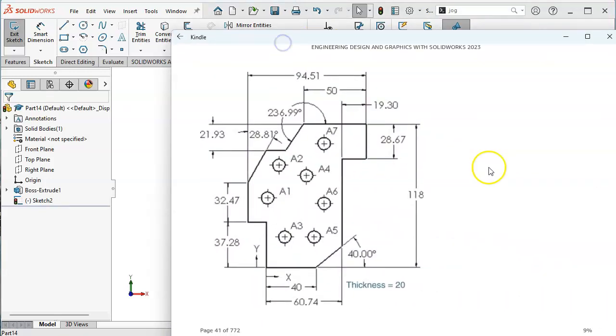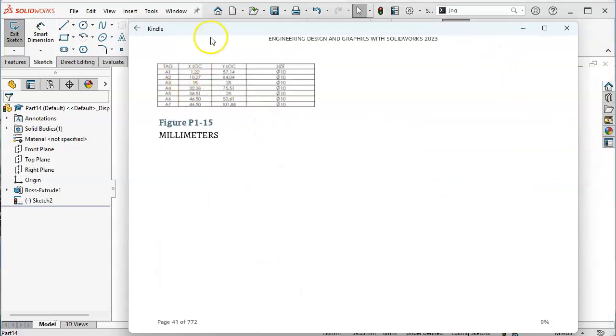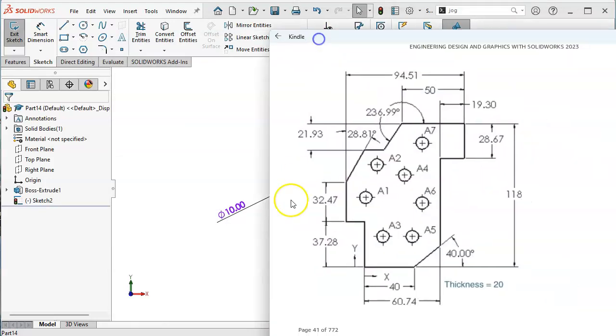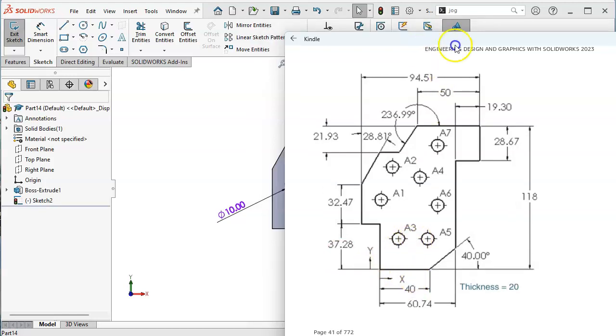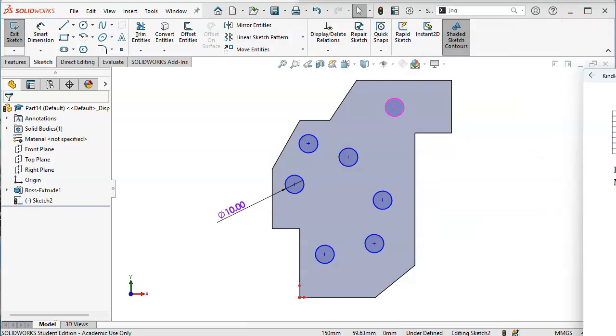All right, now the fun part in setting this is I could end up with a bunch of baseline dimensions. We also need to figure out where this is generated from. So the XY datum is off of this point, which I made the origin. So this is also going to lend itself on the whole table to this ordinate dimension scheme. So let me fly that one back in.